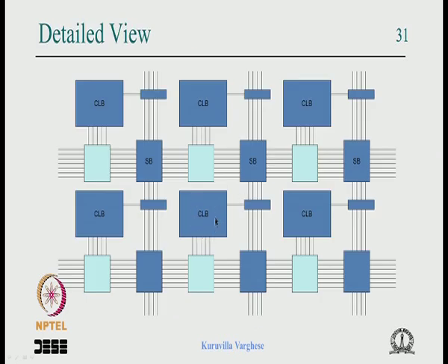So it's a configurable logic block, and you can see that there are switches between this input wire and the output wire and so on. Okay. Similarly this shows an output of a logic block coming to a switch here. It essentially means you can connect this output to this input, this one or this one, or maybe this side, it doesn't matter, you can connect it either way, or sometimes it's a single line to which it is connected, or there is a disconnect depending on the number of outputs and so on.